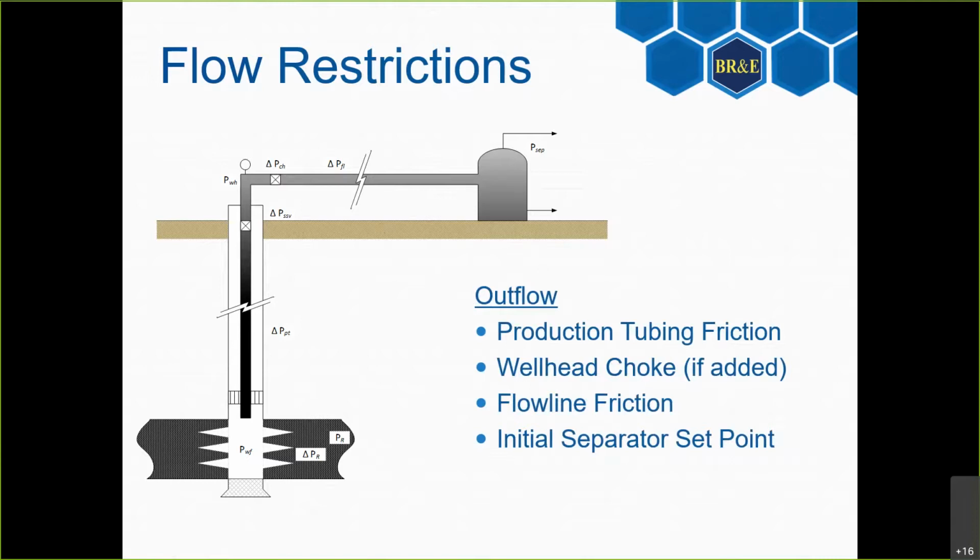It also helps insulate, in some cases, the facility operations from the production levels. So we'll talk a bit more about what that means. But when you're in a choke flow setting, the idea is that our downstream pressure doesn't have as big an impact on our choked flow, or the flow that we can force through that choke valve. And so it gives us a little more operational flexibility on the facility side when that's not the biggest determinant on our production levels. So for multiple reasons, wellhead chokes are common.